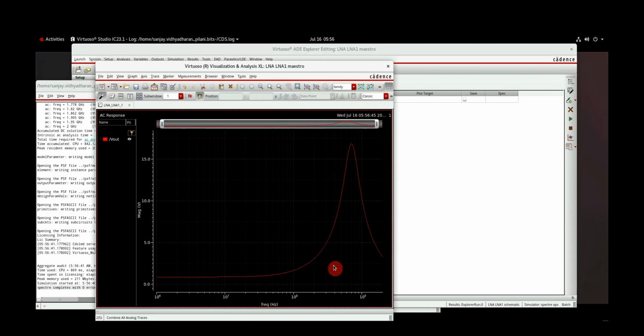So this is the plot I get, right? If I put a marker out here, theoretically when we calculated just LC, it was around 711, but maybe because of the additional capacitance from the MOS, or because we are taking 100 points per decade.